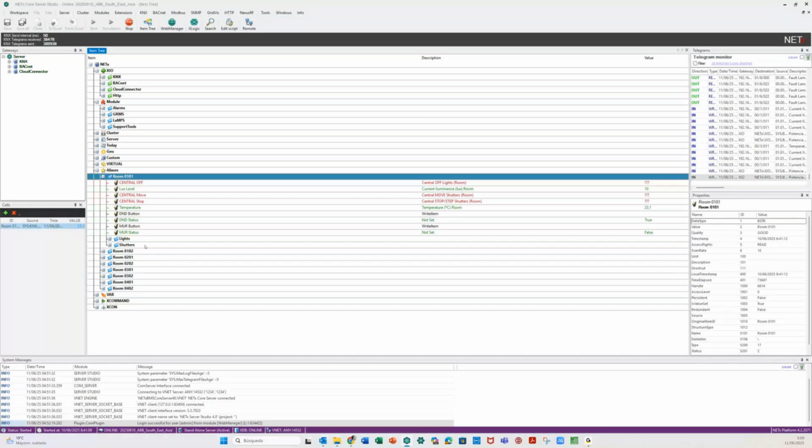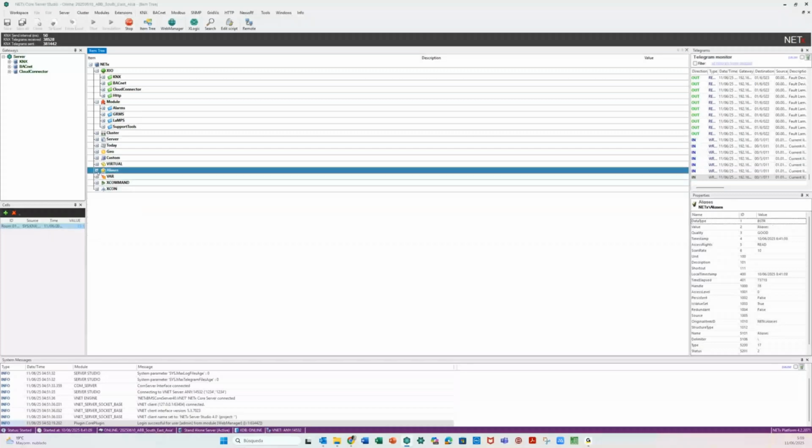It was a first approach, because there is a second one, which is to use virtual items. But there is a slight difference between aliases and virtual items, because aliases are totally free of cost. Aliases are just a representation of the items with the name, structure and order you may want to use. In this case, we had different things from every single room, mixing KNX and BACnet. At the end, we will have a lot of data points, but all of them are items in the same tree.